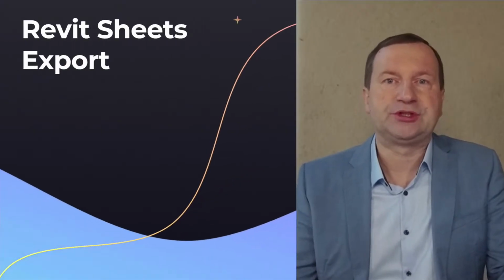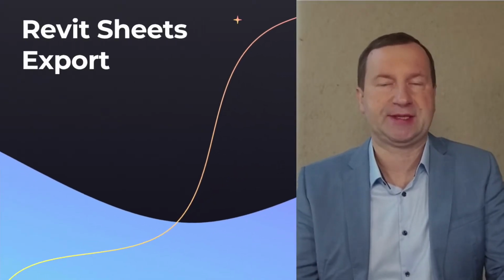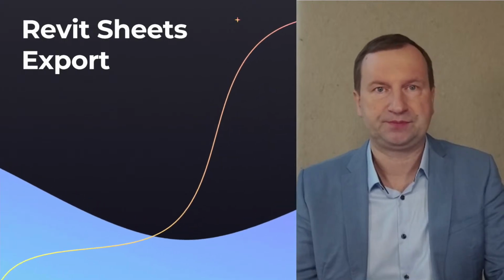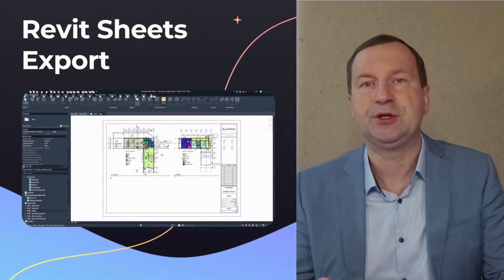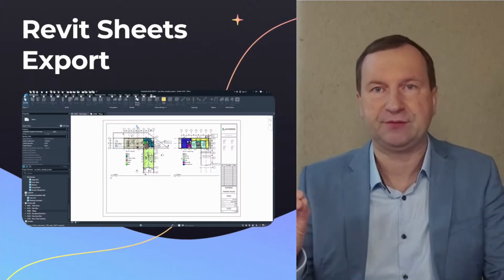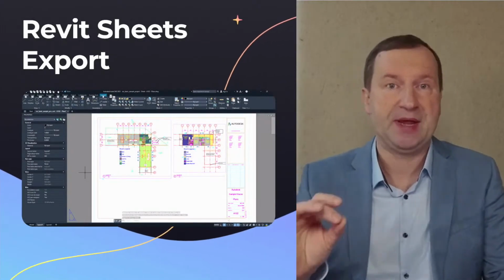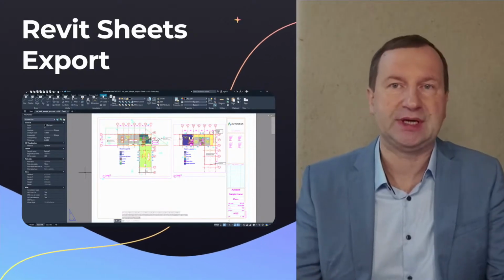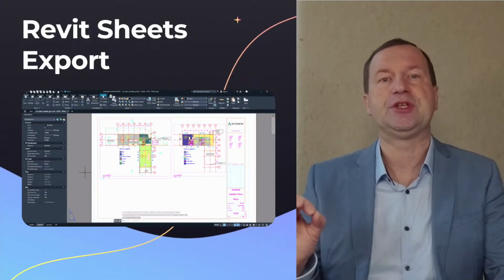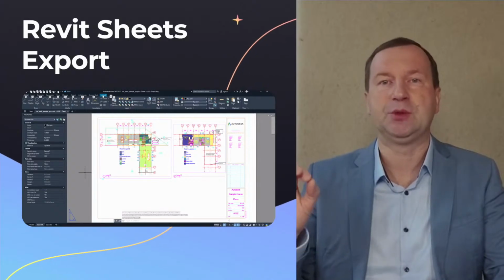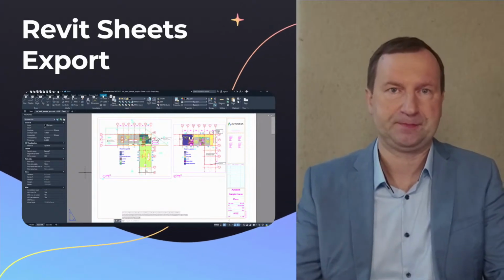As it's well known, Revit has the ability to export data to DWG. This functionality is particularly popular for a type of Revit view called sheets, which are similar to DWG paper spaces. Consequently, Revit exports its sheets to DWG paper spaces.